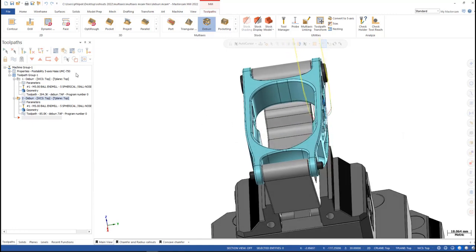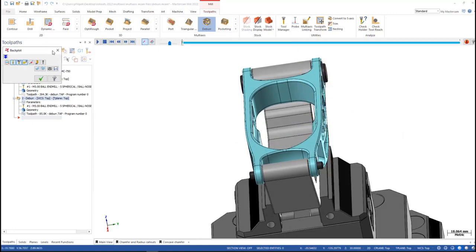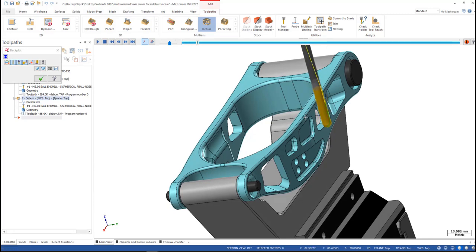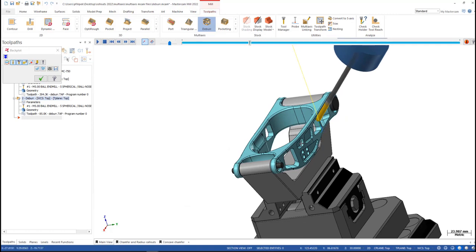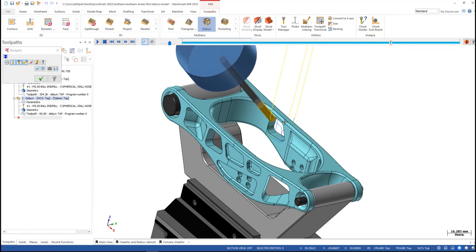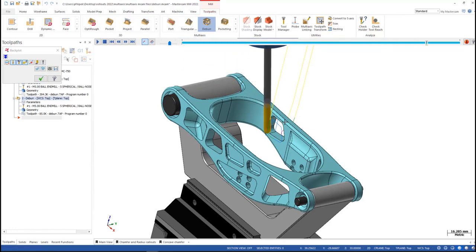And I have a tool path there. So let's go ahead and take a look at what we get. That tool path is going to come down, and it's going to do exactly what I would expect it to do, tilting the tool out and cutting around this edge, giving me my 0.5 millimeter of edge break, and it'll also go inside here and do the same thing.